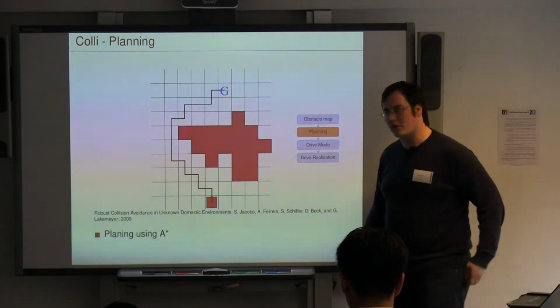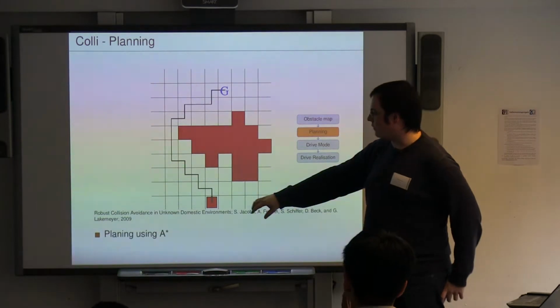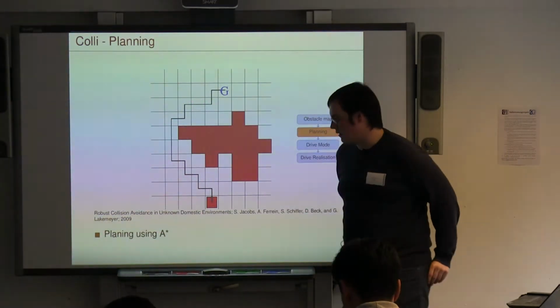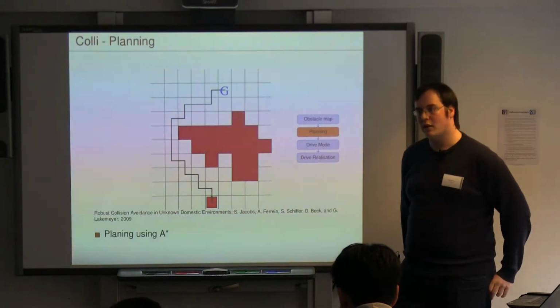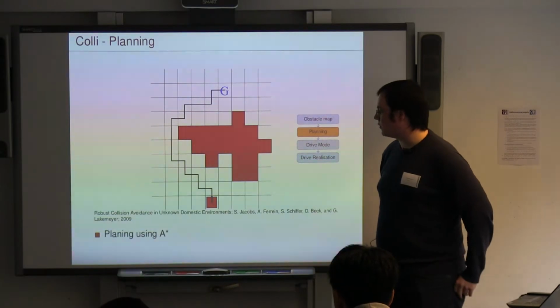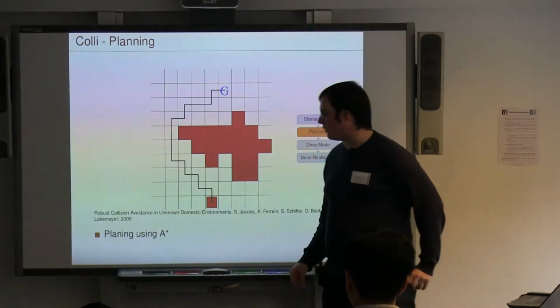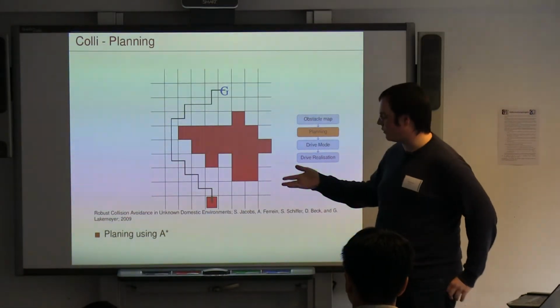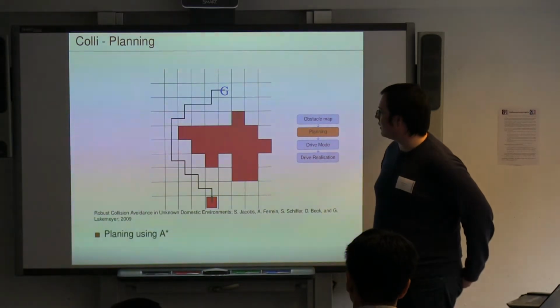And then on this grid with the obstacles put in, you calculate your paths. For that, we use the A-star algorithm again. This time with the Manhattan distance as a distance between the nodes. So each cell is a node, as before in the graphs that we used to calculate the algorithm in.